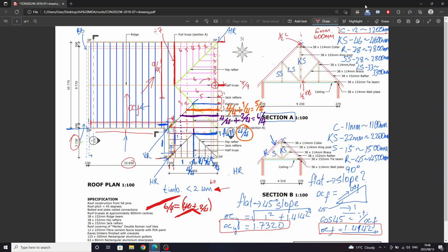That's what's happened here, is you've got this goes up, it comes back down, and you've made it whole, and you've said, well, it's 6/4, and you've applied your 6/4 to your rafter length, and I don't have the rafter length in front of me, but it was scaled. I scaled it. Oh, it's right, it's there. Okay, here's your rafter length, was 7,800.